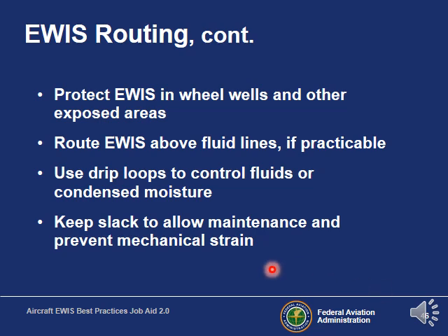This last point talks about slack. You want to make sure that you have enough slack in the wires to prevent mechanical strain. If the wires are too tight, then they could cause damage.